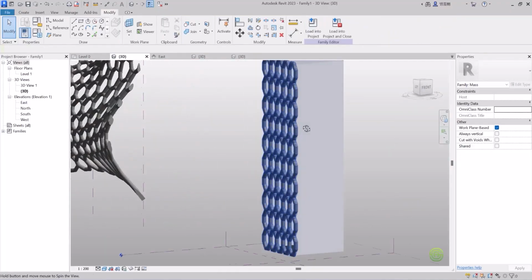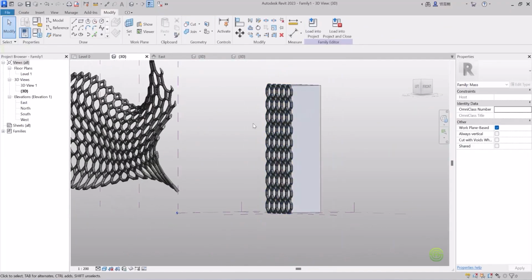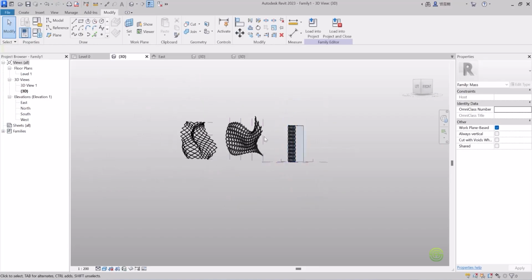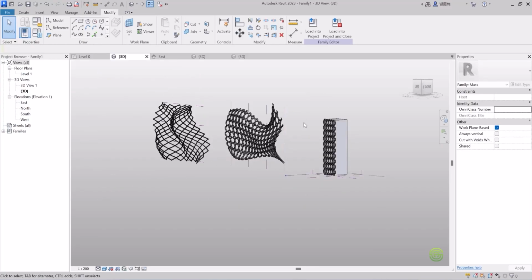So now for a plain rectangular surface also, we can create a thickness to the patterns like this. If you want to create a jali kind of things, for that kind of things, you can utilize this curtain panel pattern based family to make the pattern in a thickness, convert that pattern into a thickness. So this curtain panel pattern based topic is completed. So till here, just try this out, guys. Take few minutes and try this out. In next few minutes, we'll continue with the class for the next topic. Thank you.